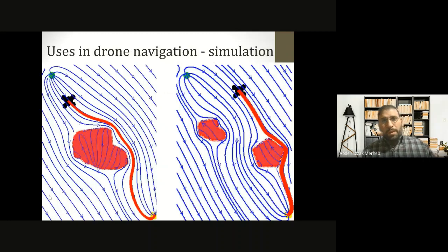We also developed a drone navigation algorithm in simulation first that accepts the map. The map has obstacles in red, the sink point in yellow, the source point in green, and the drone location in black. The algorithm accepts this map, detects all the obstacles, applies the panel method, and then gives the drone its safe pathway towards its goal point.